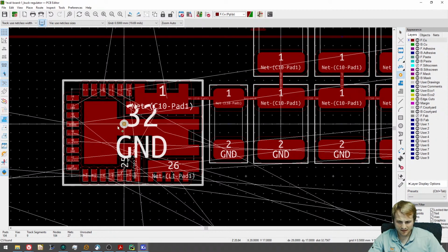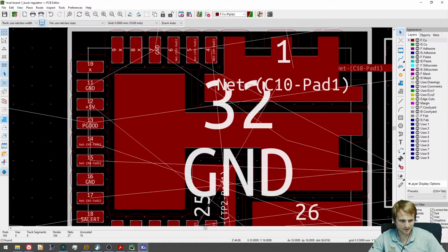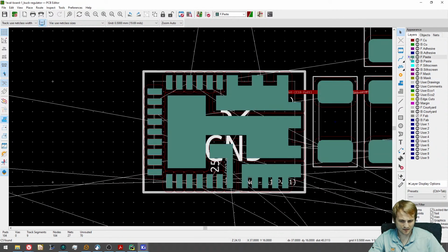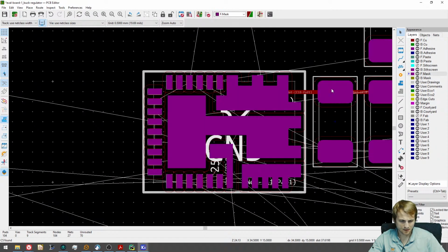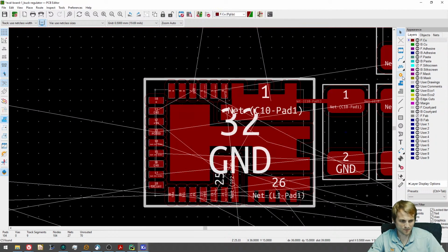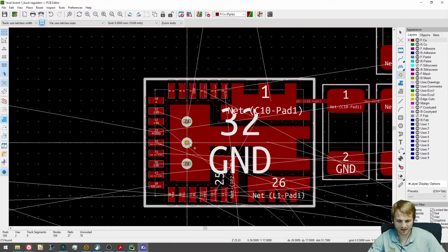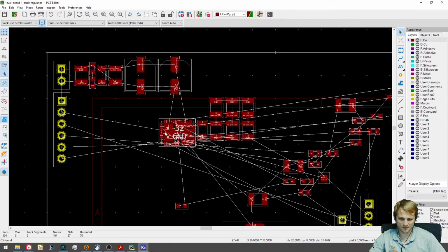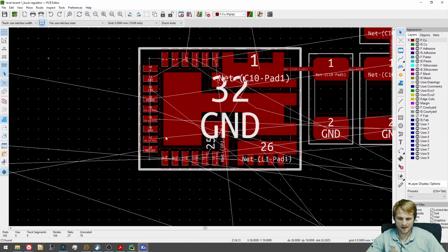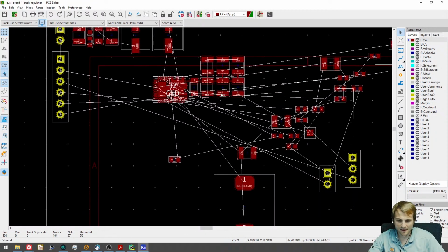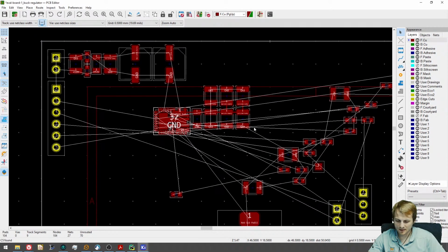And one thing that we can definitely do on this layout is have, oh, I never did, I guess I got lazy, I never did a proper paste mask and everything on here. So what we can have when I do the layout is thermal defined vias. So you can tie this straight to the bottom ground plane, which you can have massive. And that makes a huge difference for dissipating heat onto the ground. So there's our input ceramics.